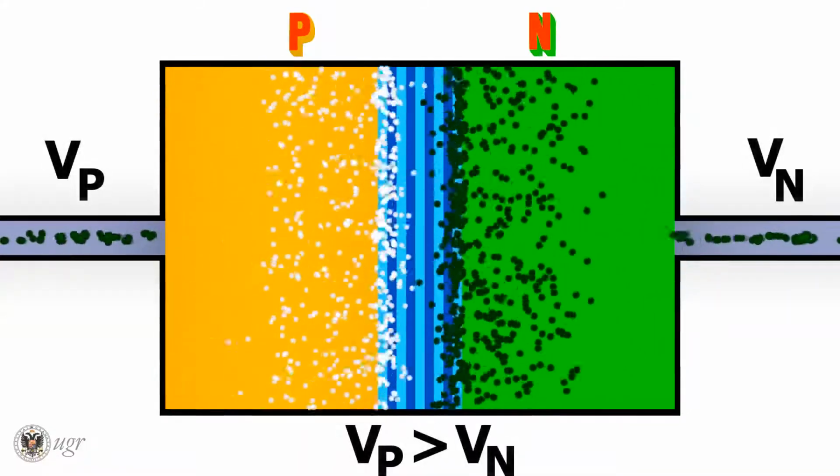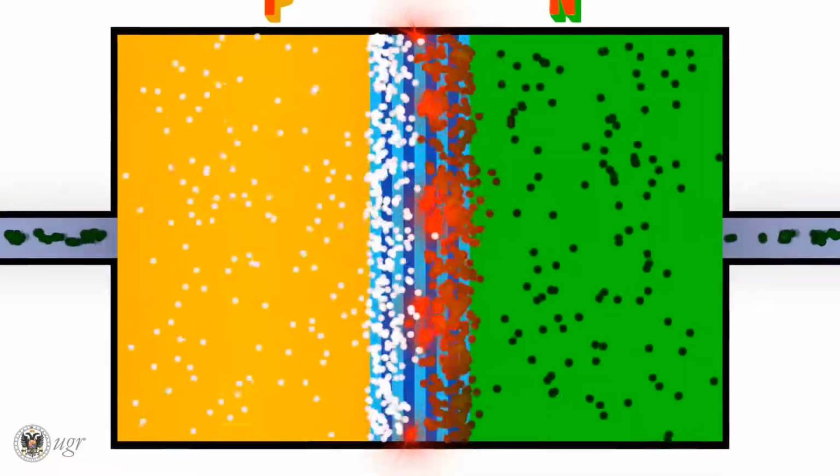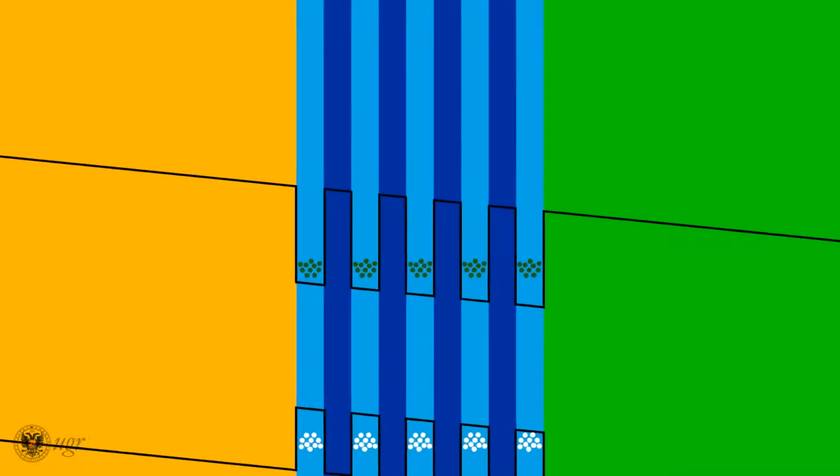To make recombination more effective, the p-n junction is replaced by a heterostructure. An active zone composed by several thin layers of materials having different band gap width is embedded in it. The band gap width in some layers is lower than in the surroundings.